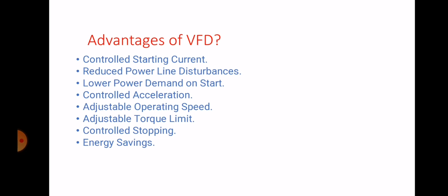And the next slide and question is, advantages of VFD system. The major advantages: controlled starting current, reduced power line disturbances, lower power demand on start, controlled acceleration, adjustable operating speed, adjustable torque limit, controlled stopping, and energy saving. These are the major advantages of any VFD system.